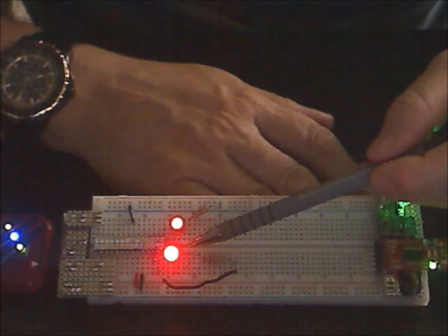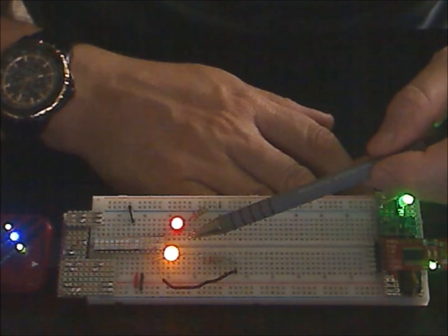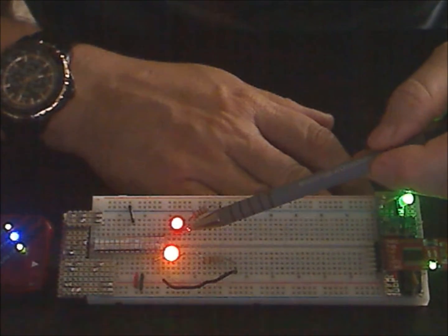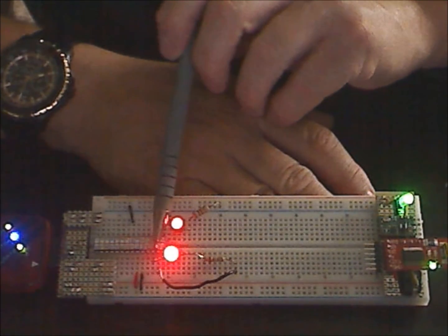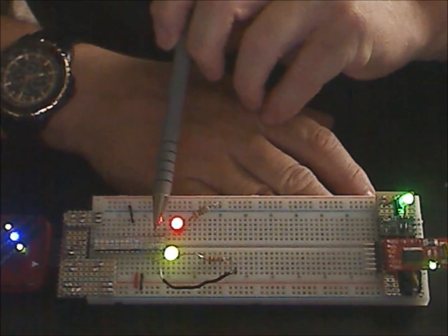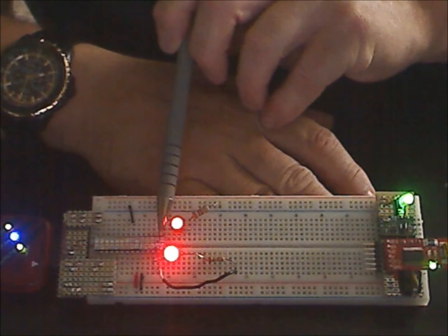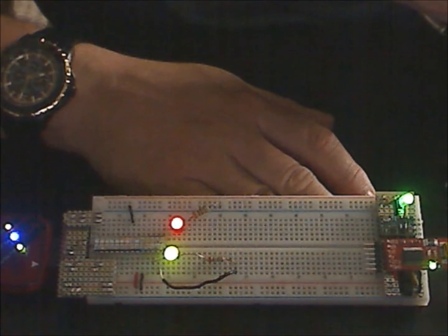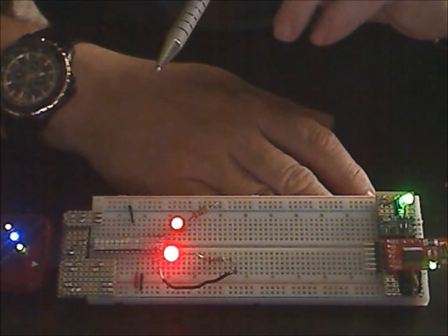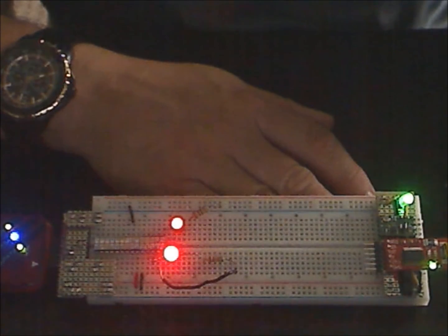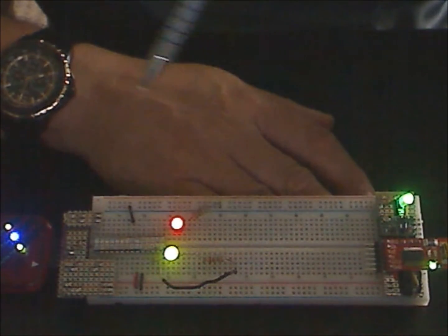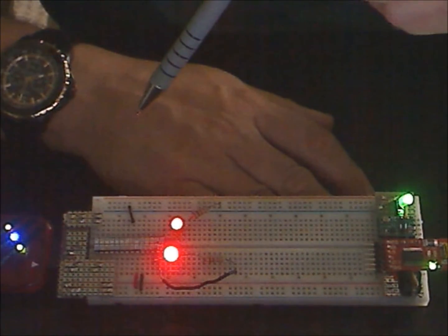A bicolor simply is 2 LEDs, a red and a green LED, in opposite directions. I'm using 2 pins. And with the 2 pins, I can make one pin high and one low. The electricity or current goes through in one way, gives me one color.